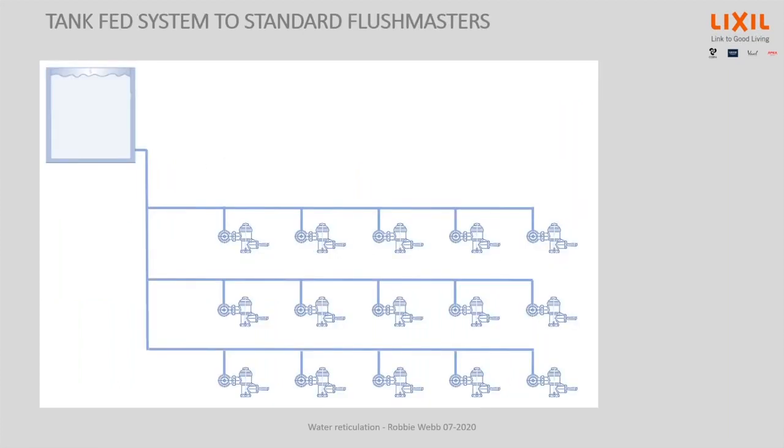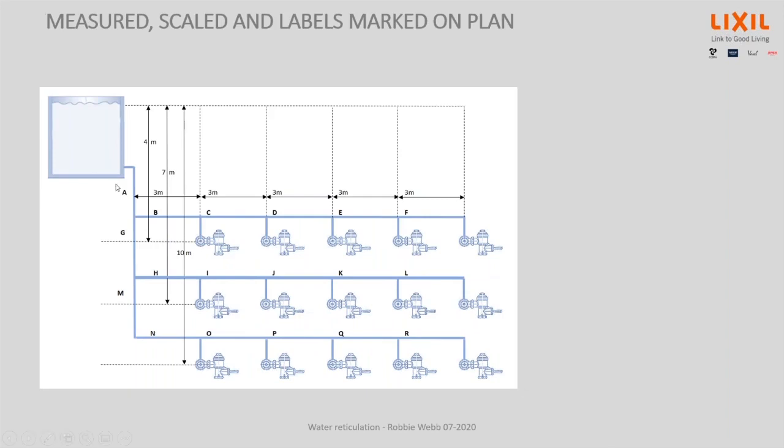So it'd be 4 meters times 10 times 9.81 if you want to be exact, would give us an available pressure of 40 kPa at the worst point. Okay, highest point, which is going to have in this case the lowest pressure. If that one works, so it won't be this one, because in this case the pressure there is only going to be 40, and in here it's going to be much better. So if this one works, we know for sure those ones will work.